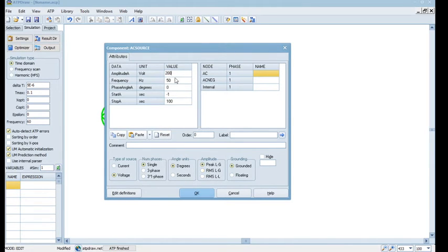Yeah. So yeah, 200 volts. Fine. To begin with, 50 hertz, instead of that we want 60 hertz. And just to start, because we want transient, that switching element, we will replace this -1 with 0. Fine. Just bear with it. Fine. A lot of mistakes happen here.